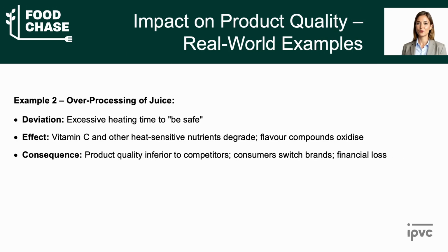Now, the opposite problem. A plant manager, worried about safety, decides to heat the pasteurizer to 80 degrees and hold it there for 2 minutes, just to be extra safe. Safety is achieved, but the heat damages vitamin C, causing flavors to become oxidized and flat. When consumers taste the juice next to a competitor's product, they prefer the competitor.